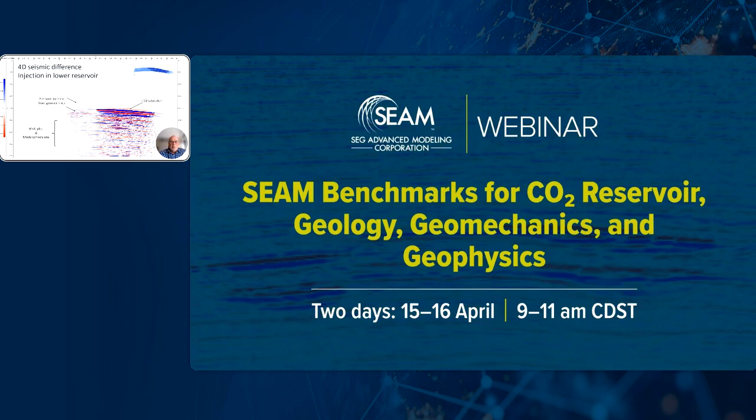So let's talk about using the data. We have got simulations now for time steps, and let's talk about how to get the differential for something, in this particular case, the lower injection of CO2 in that lower reservoir from T90 to T45. Here is the seismic difference in the injection in that lower reservoir between those two time steps. And you do, in fact, see a very strong CO2 saturation signature here.